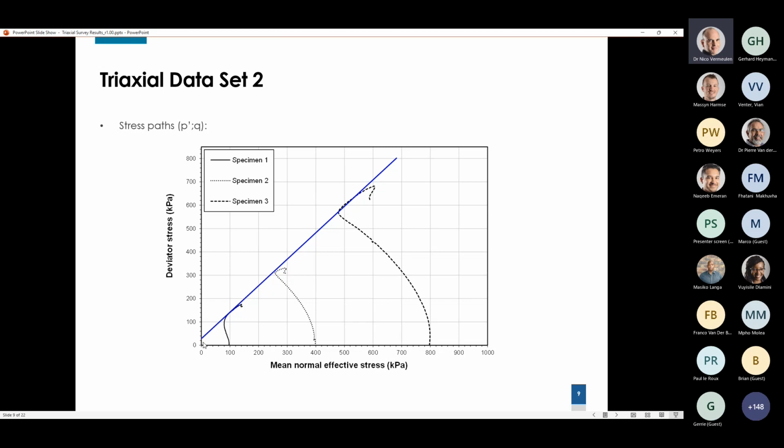It shows a little bit of cohesion towards the bottom and a friction angle that I've not noted on the slide. We could equally well, if we pick the tail ends, have come up with a trend line fit that looks like the red line. Both are mechanical fits. They require no intuition. It's just basically deciding which are the end points or the failure points in the stress path and fitting the line through it.